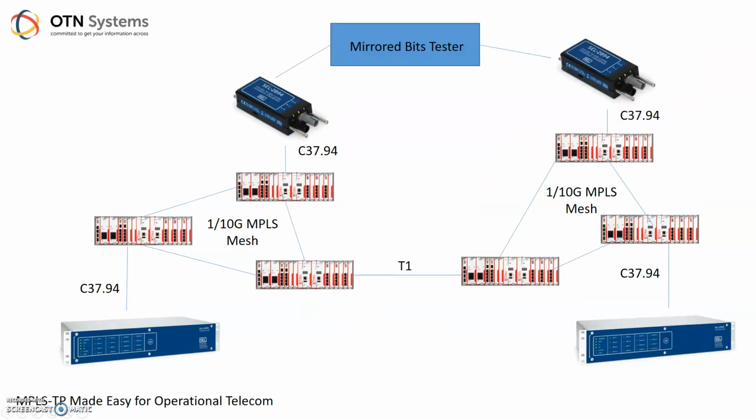In this case, what we have is this network. So what I'm going to do is set this to internal timing as if it was a JMUX, for example. This one will be externally timed, and all the remote devices, or remote ports, are going to be adaptive clocking, and I'll show you how to do this in TXCare.